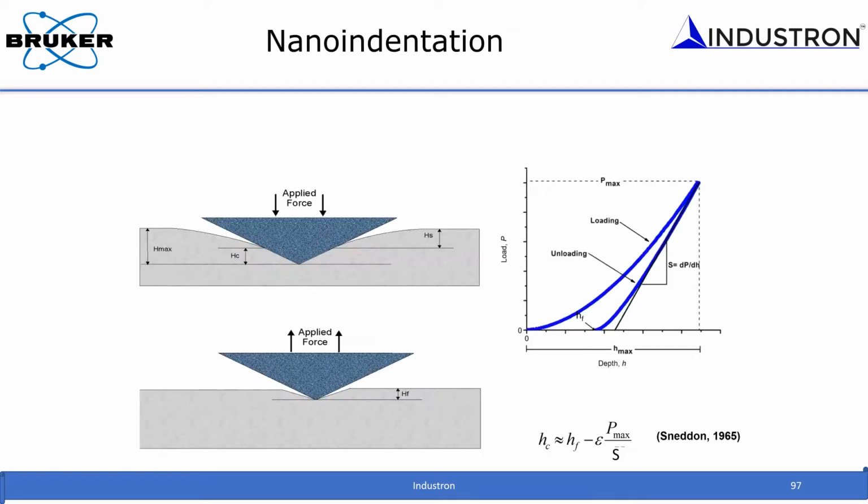So I think it's better to go through what we did in the last two webinars. I introduced the concept of nanomechanical testing by doing a depth sensing indentation technique where you use a rigid probe, apply a stress onto the sample, and then measure the load displacement response. And we can deconvolute the mechanical properties from this load displacement curve. That is the fundamental that we covered in the first webinar.